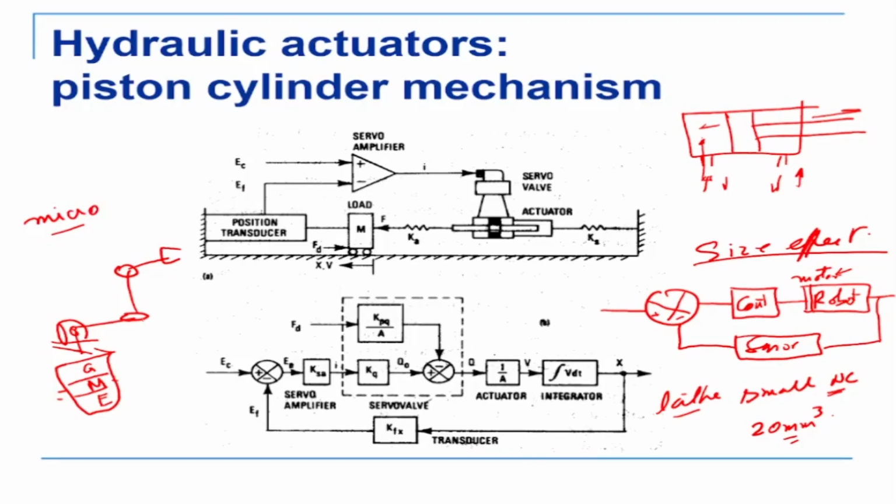Okay, but if I make a small DC motor, this DC motor will not have enough power to move the links of the robot, because in the DC motor, the torque is equal to the motor constant times the magnetic flux, the strength of the magnetic flux in there. So for a very small DC motor with a very small magnet, it will not have enough strength, and hence it will not have enough power to move the system.